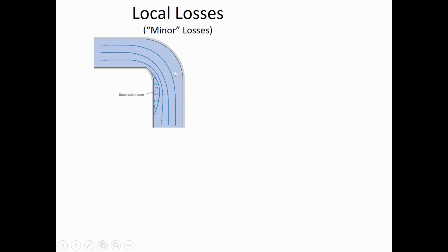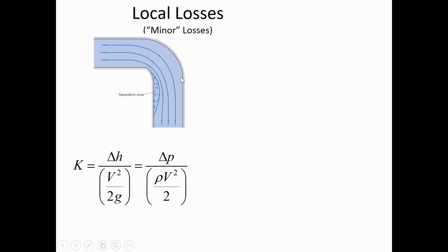If you have like an eddy where a certain section of the pipe, the water is going the opposite direction, then that means that the actual effective flow area has a smaller diameter. And so you're forcing the flow through a smaller effective flow diameter, then that's going to reduce some energy. It's as though the pipe is smaller for a certain section.